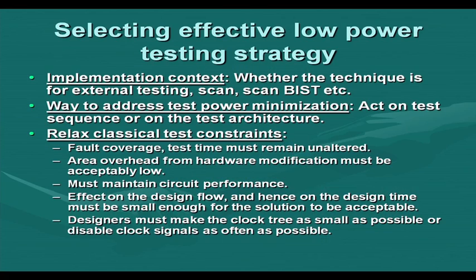And if we can disable the clock signals, then power consumption will be low. That way the test engineer may have some relaxation. If these classical test constraints are relaxed a bit, then power consumption during testing can be reduced significantly.